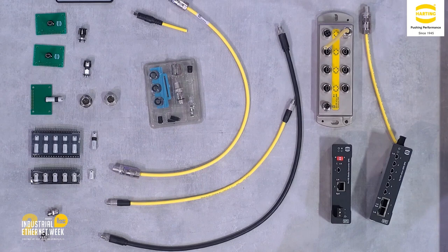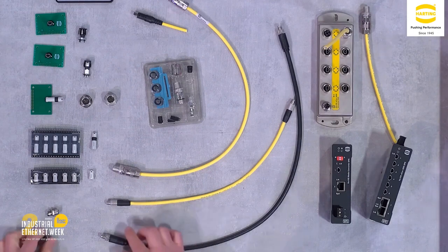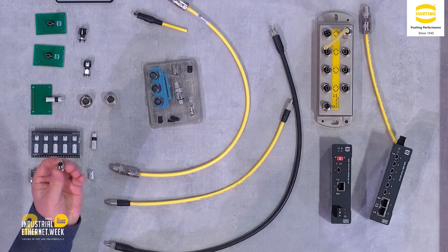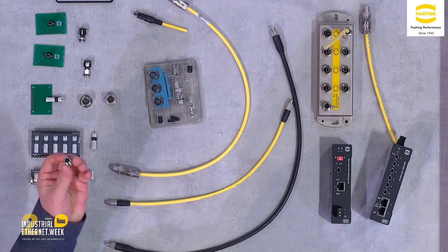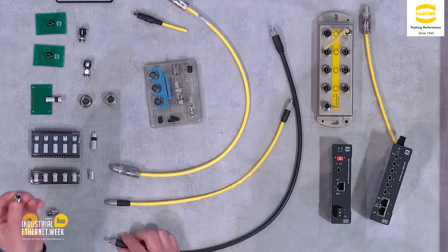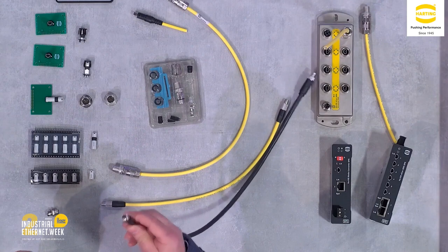All these products are also compatible with PoDL remote powering, and you get some more information in one of the next presentations. If you want to have power separately because you need more power than PoDL can offer, we also have this very tiny M8 interface, the M8 hybrid, and here we have 4 contacts, so 1 pair for data and 1 for power. Here we also have the device integration, and we have the cables and connectors for this.